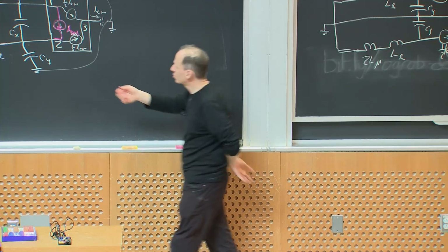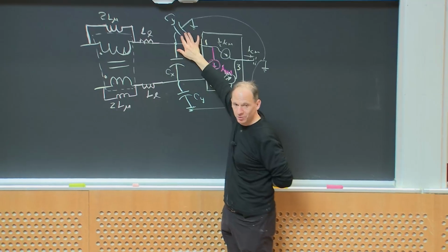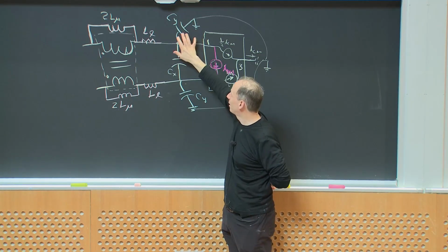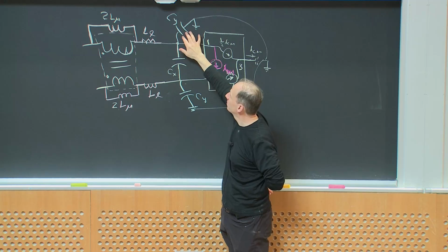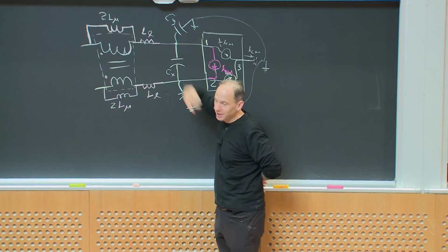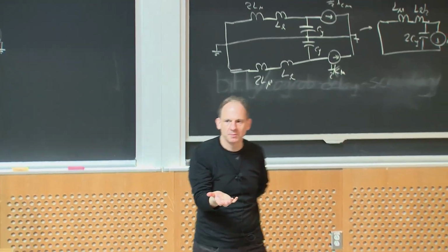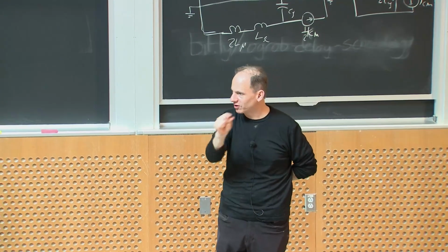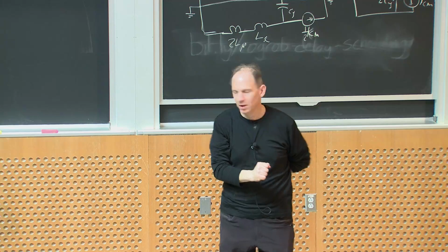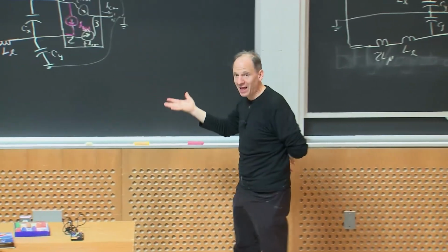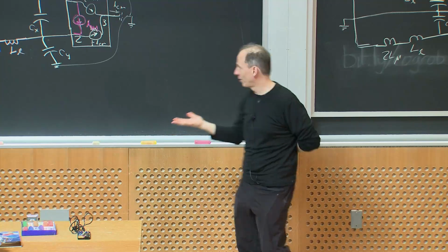So they put very strict limits on how much current you're allowed to put into ground, and for 60 hertz currents, which is what they're really looking at, or 50 hertz in Europe, this Y capacitor is very limited in value, depending upon the application. You might be talking like 5 nanofarads, very, very small capacitors. So I don't get a very big capacitor value that I'm allowed to use. How do I get all my filtering?